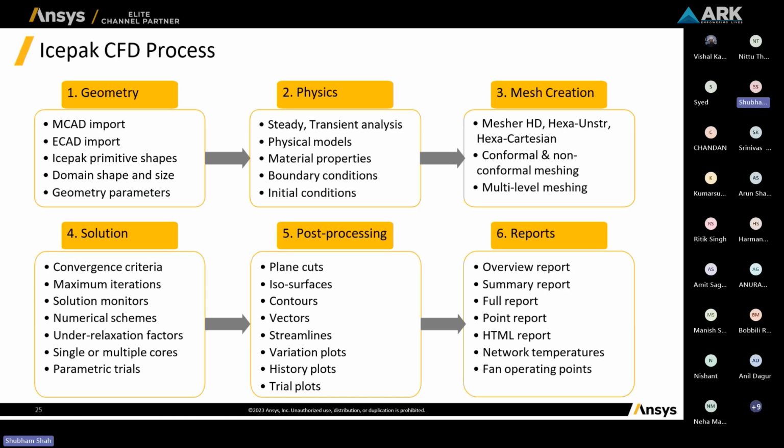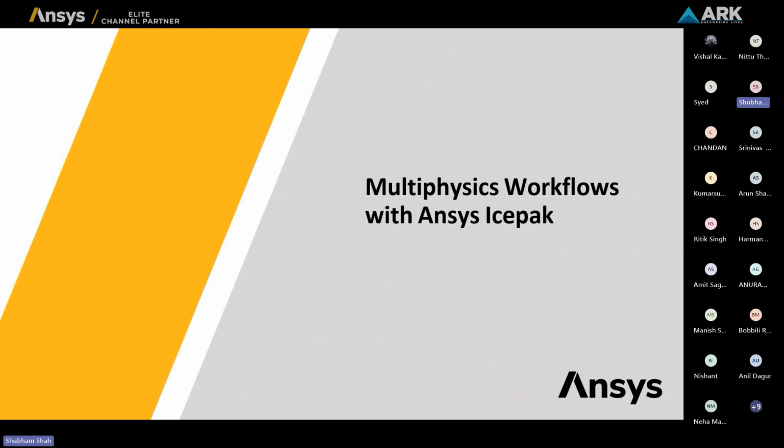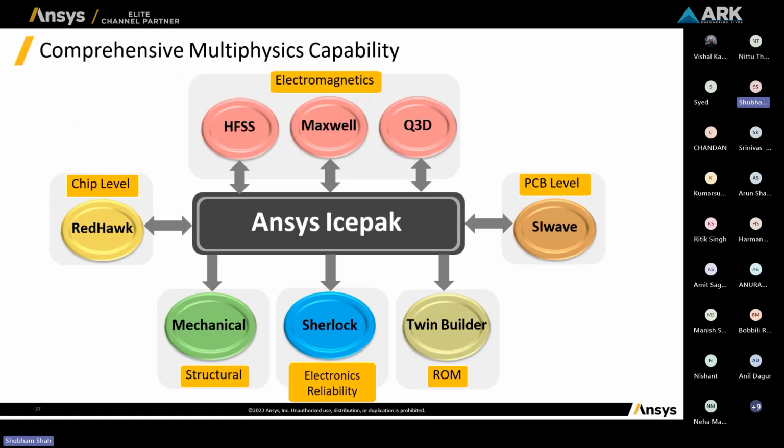So report generation is also available in terms of HTML reports. This is the multi-physics workflow with Icepak. When it comes to Icepak, you can couple it with electromagnetics, whether it's chip level, RedHawk is available, whether it's for PCB level, SIwave is available. For mechanical, structural is available. For electronics reliability, the Sherlock tool is available. For ROM, Twin Builder is available.